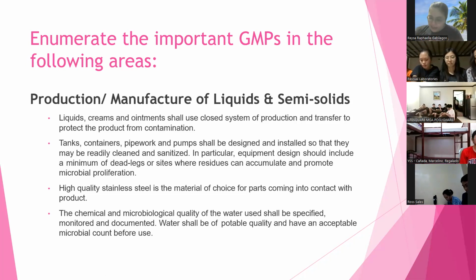So there are tanks, closed containers, and pipes for these solutions designed and installed in the manufacturing plant so they are easily cleaned. The engineering department plans so that equipment is easy to clean and sanitize, with no contamination and minimum dead legs. Dead legs are pipes where liquid or even water does not flow, like a pipe that just ends closed. If a company has many dead legs in its pipelines, there is greater proliferation of bacteria, because it is a dead end and water can collect and no longer flow.